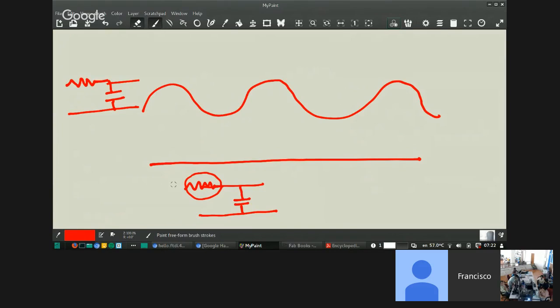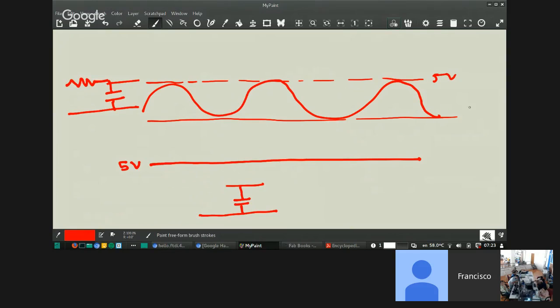No, I'll tell you what. So you have 5 volts. You supply 5 volts over the other end. See, the left side of the resistor, suppose you have 5 volts. Yeah, but this can also be, say, 5 volts. Here you will get 5 volts as long as you draw zero current. But the moment you start drawing current, say you draw 100 milliamperes, then you won't have 5 volts. There will be a drop across the resistor. Suppose the resistor is 1 ohm, then 100 milliamps into 1 ohm is 100 millivolts. So what you will get is 4.9 volts on the other end.